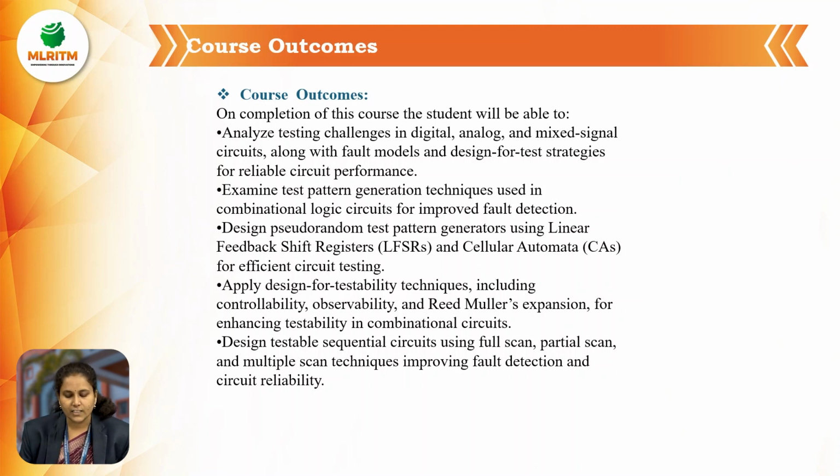Apply design for testability techniques including controllability, observability, and Reed-Muller's expansion for enhancing testability in combinational circuits. Design testable sequential circuits using full scan, partial scan, and multiple scan techniques, improving fault detection.